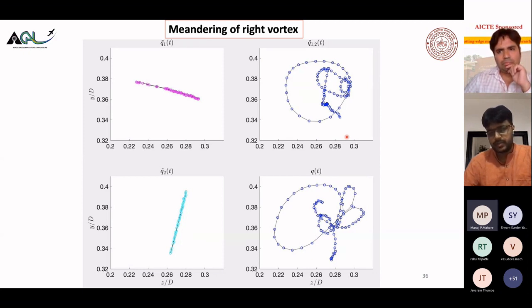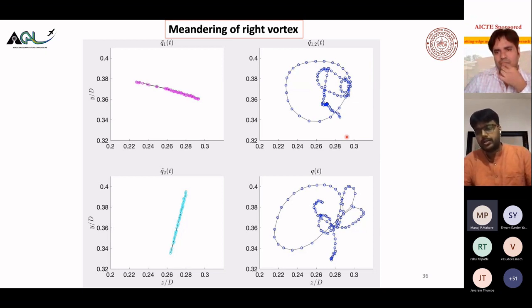The boundary layer we got from the experiments, and we just imposed it there. So the inlet is somewhere away from the body, ahead of the base, right? We just put the boundary layer that we get from the experiment. It can actually do the flat plate boundary layer also, and put it there. Then you have the wall condition on the base, and away from that, you can have a symmetry condition or anything. If your domain is very far from the body, you can have an open boundary condition there.